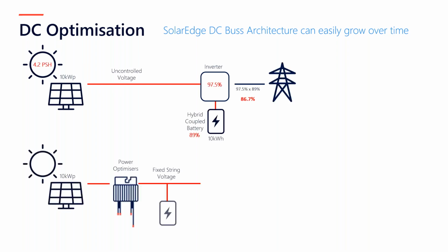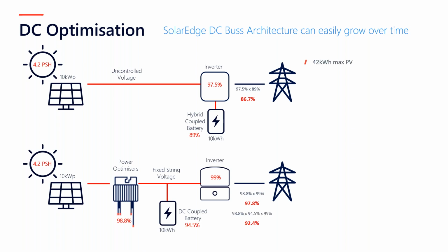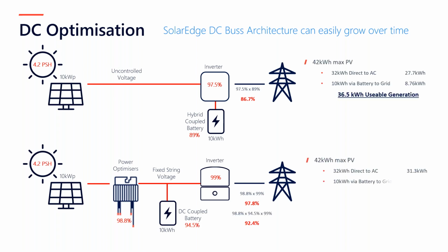And I'm just going to move through this quickly, but this also is a worked example comparing the differences between traditional DC coupled hybrid technology and that which we see with our own systems. So again, we run at fixed voltages, and because the battery charges at the same voltage as that which is generated on the roof, it's extremely efficient. And it's quite different to that which you see with traditional DC coupled hybrid inverters, where there's some sort of voltage management or step down or step up effect, which can be nearly as inefficient as a DC to AC inversion step like we see with AC coupling.